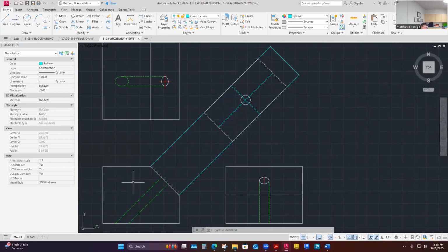I've got to restrict it so that it matches the surface length here. And then the width here, I should say the depth here, is going to be driven by the depth of top and depth of right side. So that is going to be in common with this particular auxiliary view. What's in common is that I'm projecting from the front view. I pick up my true length of that surface from the front view, which allows me to build this projection binding area where the shape's going to be bound. And then I can pick up the depth dimension from the top view and the right side view depth. So I have some given information and some I develop myself. And yeah, so that's what I've got going on.